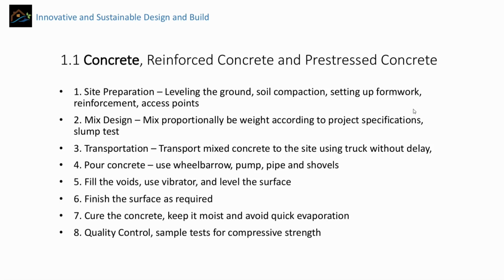The amount of vibration is also important, and we should not vibrate too much because it segregates the elements, and bigger aggregates go down, and then the water and cement just rise up to the surface. Properties change in different locations, and if we use vibrators more than the desired amount, then these property variations might be higher, and therefore there is a limitation on the use of vibration.